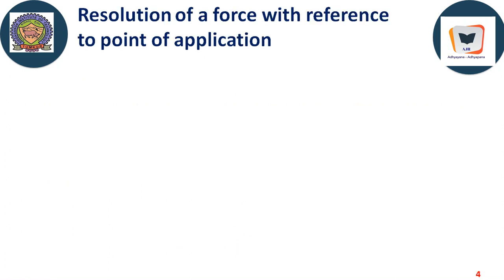Right. Resolution of a force with reference to a point of application: we need to resolve a force keeping in regard what the point of application is. Point of application really matters when we resolve the forces. And here this inclined force F is acting at this particular point. Therefore, looking into the sense of this force, horizontal component will be rightwards and vertical component will be upwards, and this is positive y and this is positive x. Fx equals F cos theta and Fy equals F sin theta.